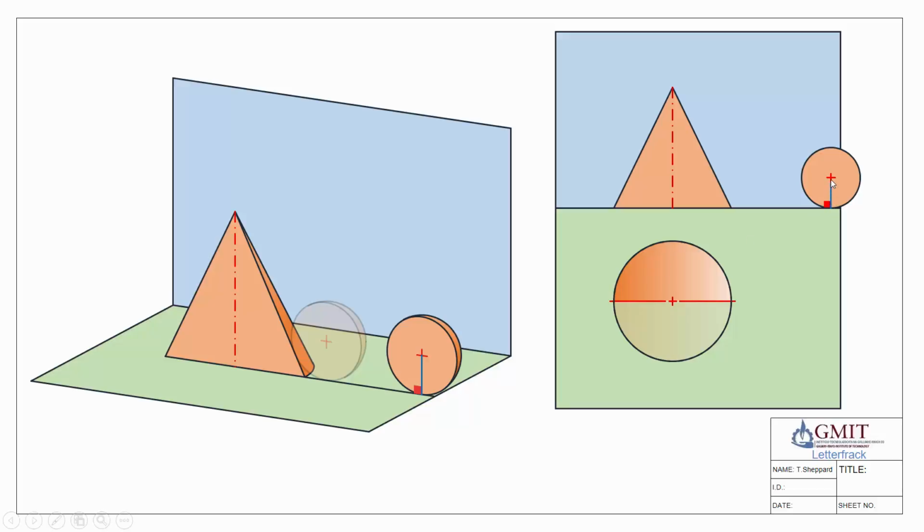So we come up our 20 millimeters here to draw in our sphere out to the side at the start, and we kick it along and roll it along the ground, giving us this parallel line. And you can see I haven't stopped the line at this point here. I've just continued it on because at this point we don't really know where this line needs to stop. But we do know that every sphere of radius 20 millimeters with its center on this line has to be in contact with the ground, or horizontal plane. So we've done that for our sphere in contact with the horizontal plane.